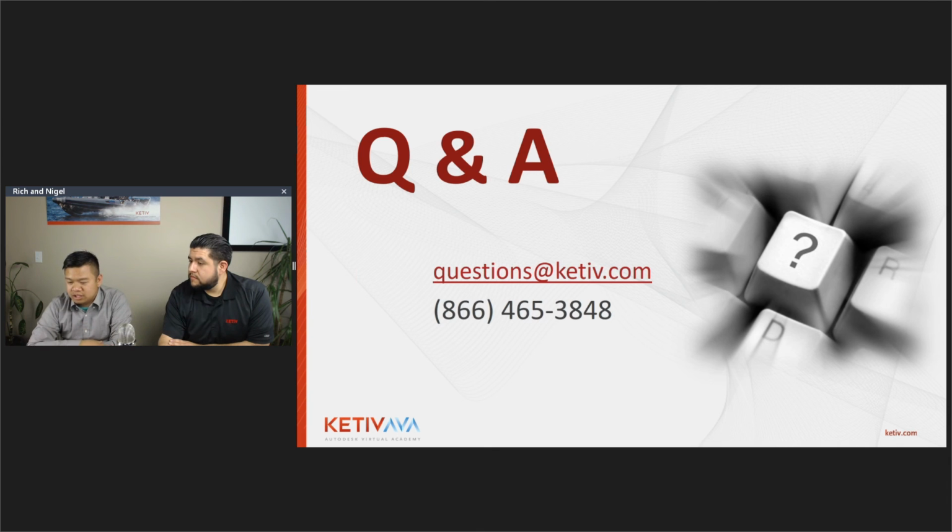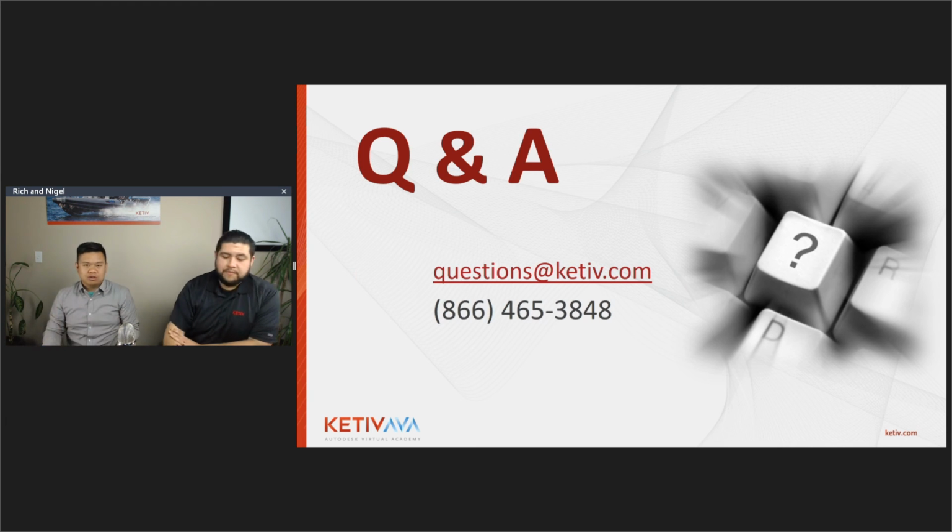And the question is, can I do anything besides a quad? So a square or a rectangle in regards to the crop? And I can answer this. You can do things that aren't quads if you really wanted to. There is, I believe, a sketch that gets made on that cropped view that you can edit to change what your shape is. So you can always add arcs, you can make circles, you can do whatever you want to your crop view. If you want a rectangle minus a little bit at the top, you could always do that.